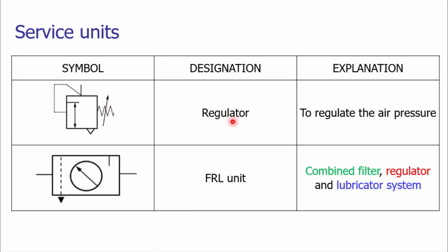When the system pressure increases beyond the critical pressure, the set pressure, or what we can call the cracking pressure, then the compressed air has to be vented out. It has to be sent to the environment. For that purpose, a small open triangle, not a filled-in triangle, is there at the bottom side, giving the indication that the compressed air has to be vented out.